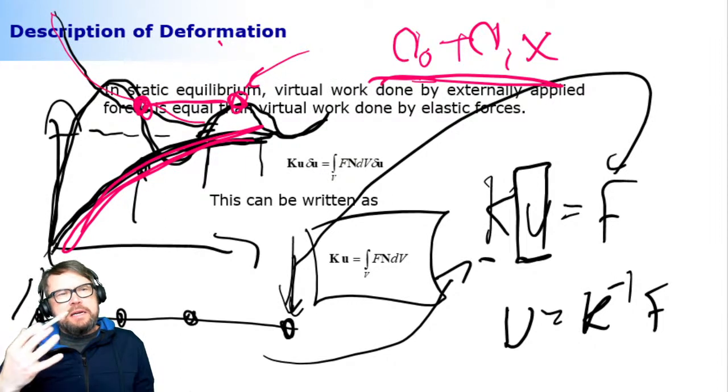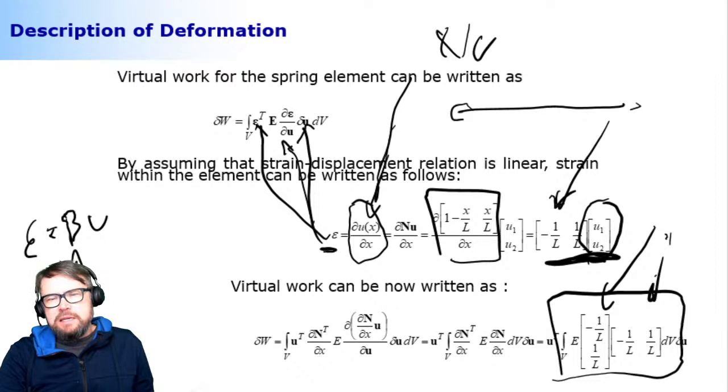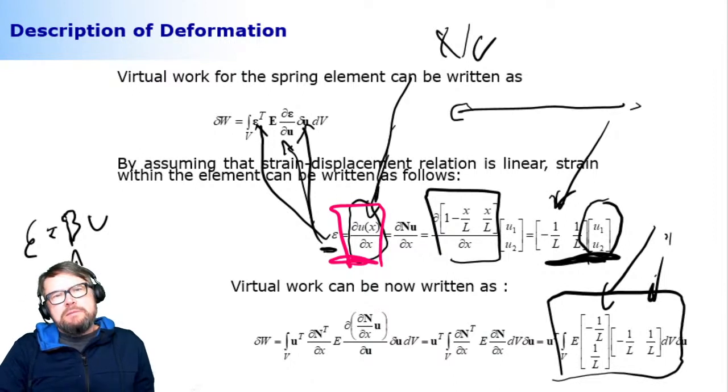Constant strain is another minimum requirement. And the third minimum requirement is that the shape functions have to be continuous enough to be able to compute the components needed in a shape function. And now we're using first order differentiation, so the linear polynomial is okay. If the partial differentiation would be second order, then you would need a bit higher components, a second order polynomial.